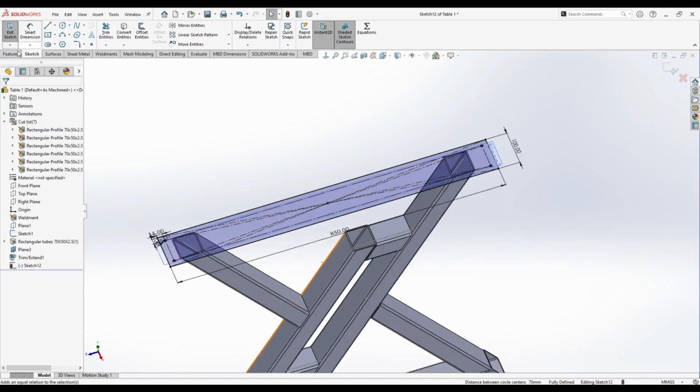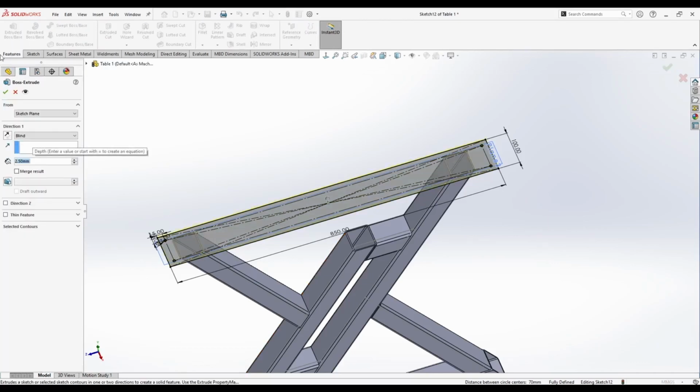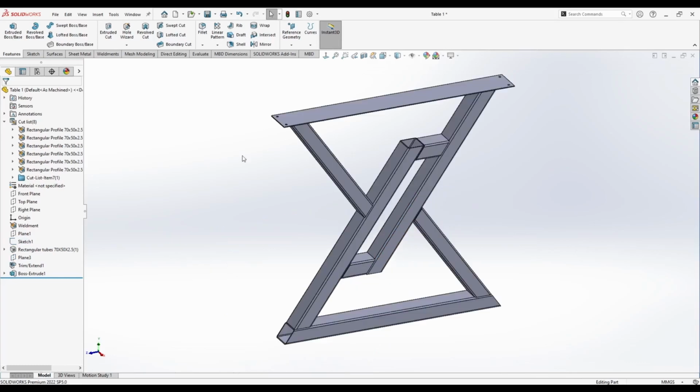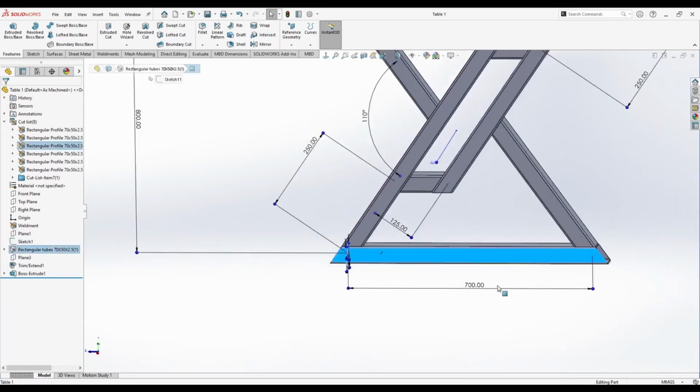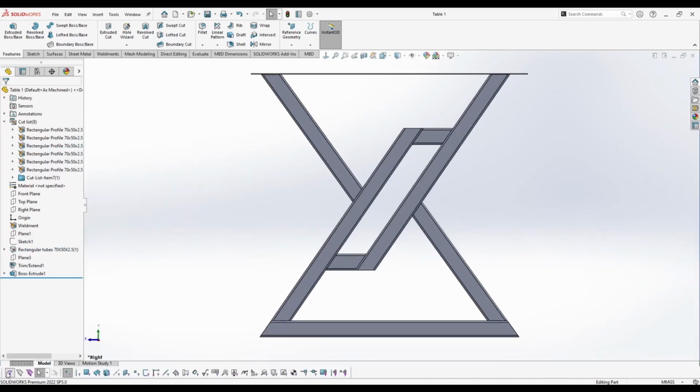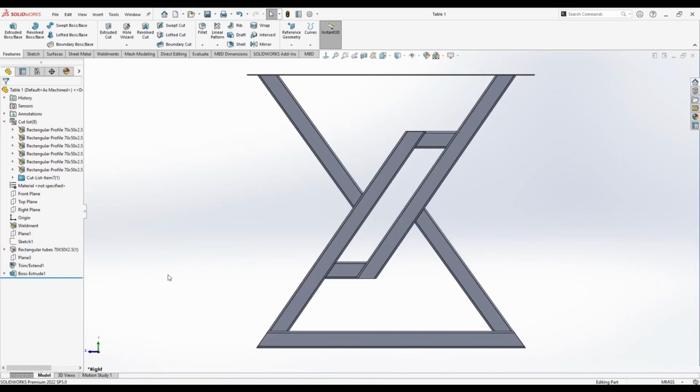In addition, we can extrude this plate by 2.5 millimeters. I can hide this plane in this sketch. Now, I don't like the way this profile looks on its ends. If this shape next to the arrow appears, you can press F5 and simply unselect it here. This is a filter you can use for sketch segments, faces, and so on. Press F5 to hide this menu.